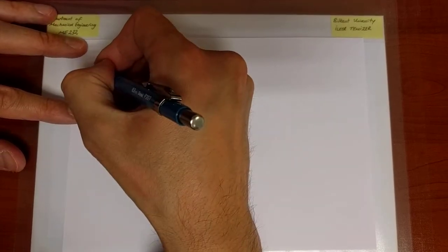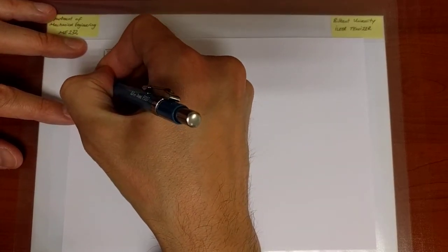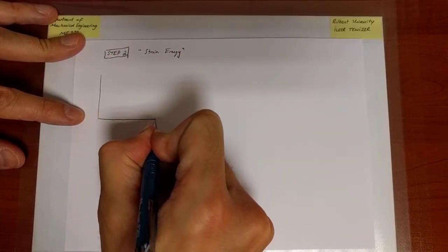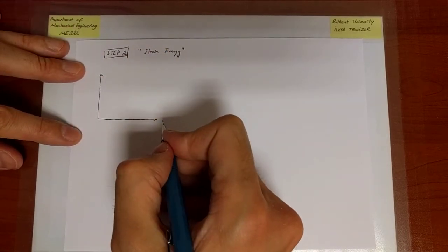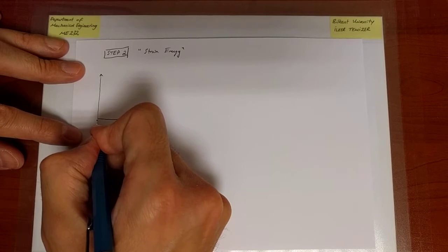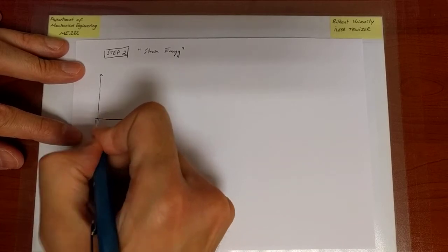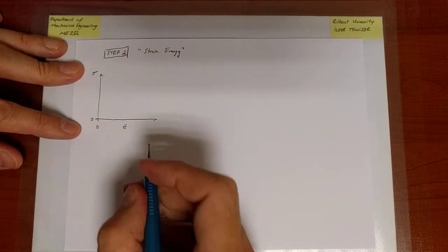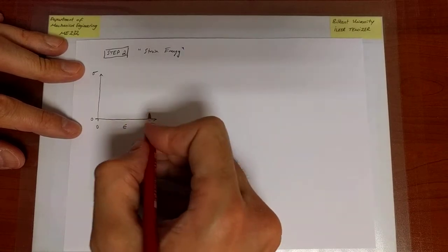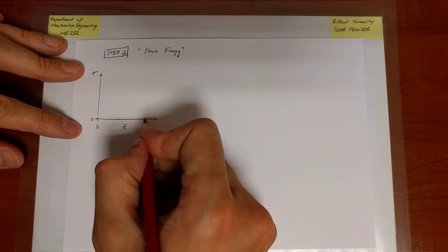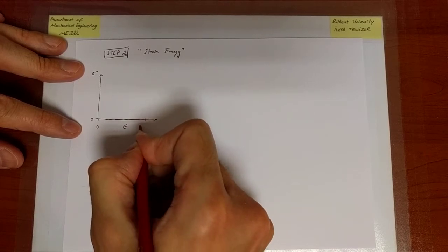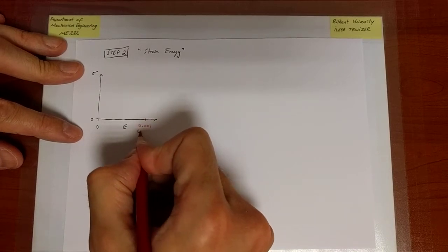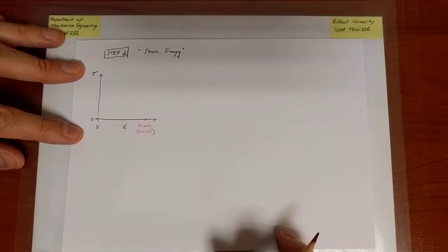So I'm going to draw a stress strain curve here that is going to be associated with material behavior where deformations are elastic and deformations are small. So I'm going to plot epsilon instead of stretch. We're just recalling what we already know, and the vertical axis is the stress. And the deformations here, I'm just going to pick some order of magnitude that's indicative of small deformations, and I'll pick that value to be 0.001, so 1/10 of 10% strain. That's certainly not a large deformation, so let's call it small.